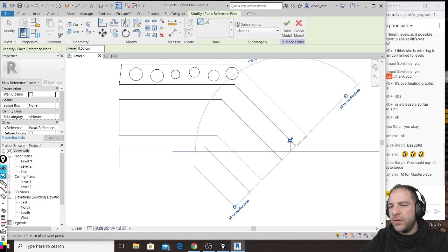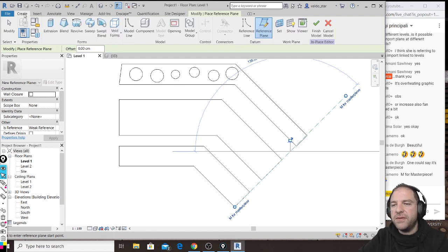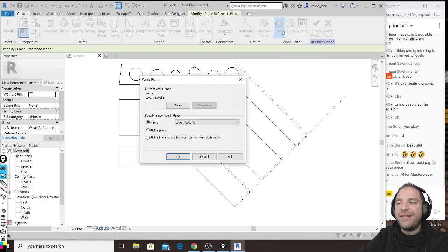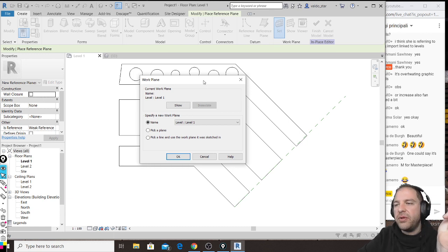This is the name of this plane here. Okay? So see the magic, because I go to create, now that I have created this additional plane, and I will click set my working plane, and the reason why I gave it a precise name is because I can now select that plane from the list of available planes, and I click OK.